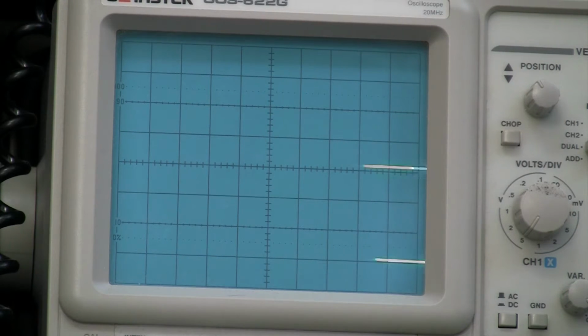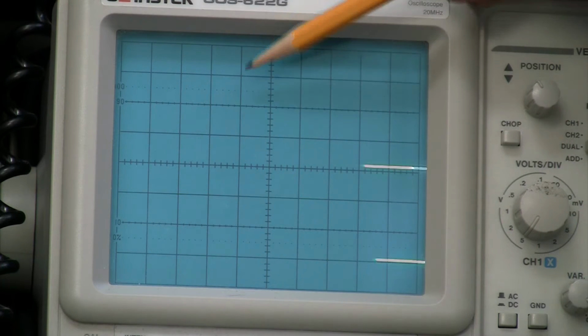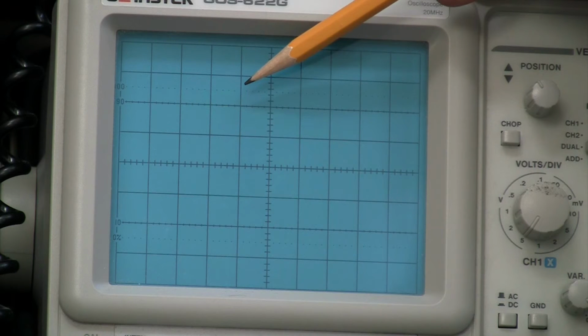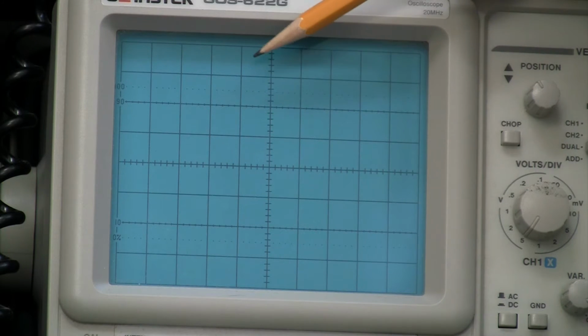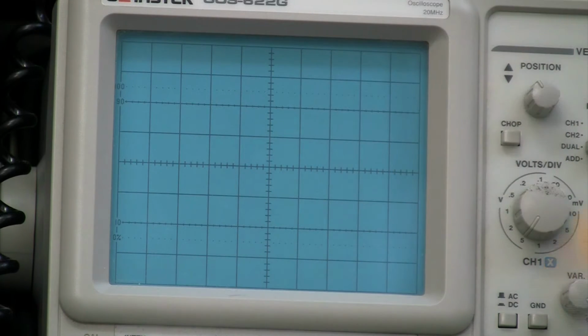Because of that we're able to do some fun things here. So with that mode set to exponential, I will get the most dramatic effect. You can also set it to linear mode and you will get an effect, but it's not as dramatic as the exponential, and you won't be able to achieve some of the things that I'm going to demonstrate here. First thing you should notice is that in the exponential mode there is a slight loss of gain. This peak right here on the waveform actually isn't quite 5 volts. It would be just slightly higher. It's probably around 4.6 volts, but if I switch this to linear, then it will actually be at 5 volts.